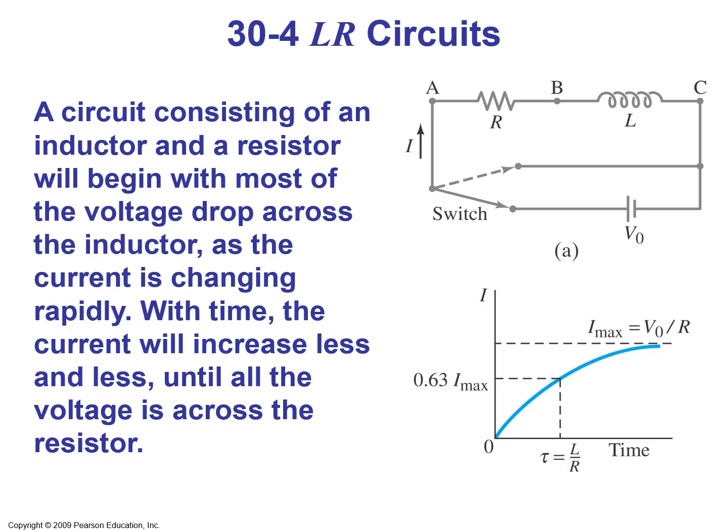So, in the figure on the right, we have a circuit containing a battery indicated with V0, connected with a resistor R, and also an inductor indicated with L. As the switch is closed and the voltage is applied, the current through this series of R and L will gradually go up from 0 to V0 over R over an infinite time.